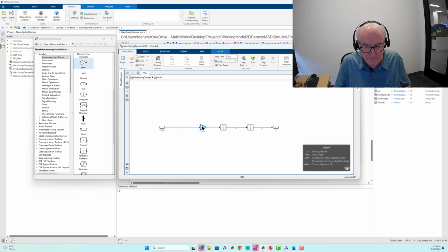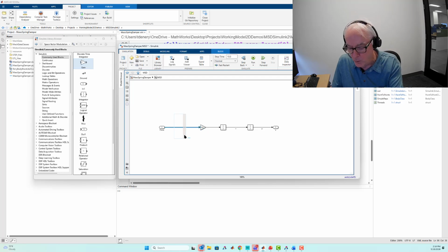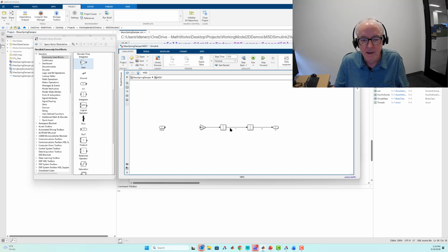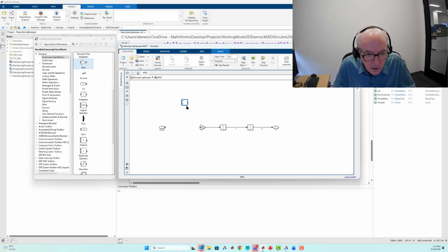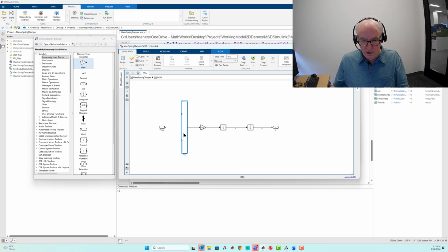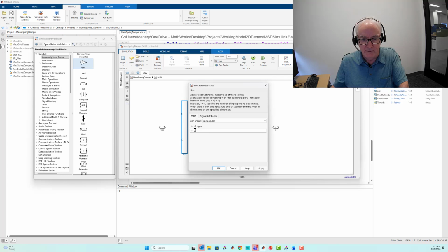And so here's where it becomes a mass spring damper, which is, well, we've got to apply the force that's actually felt by the mass, and that force is going to have some dependency on both velocity and position, right? And so we get an add block in there. Okay. All right, and so we're going to set it up so that we can accommodate both the damping and spring force.